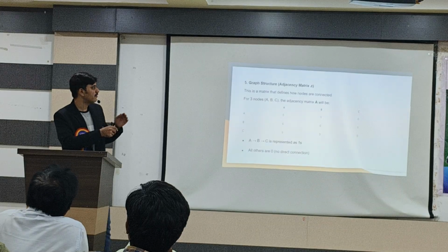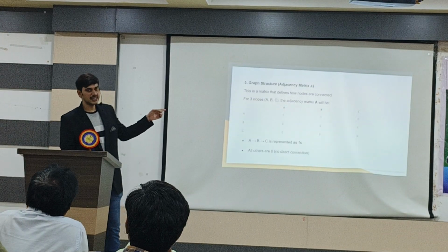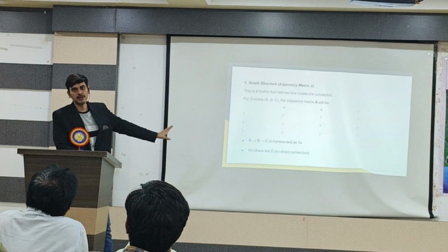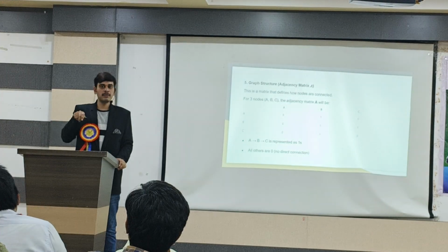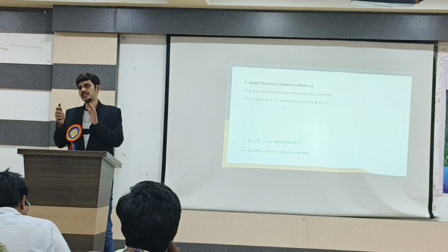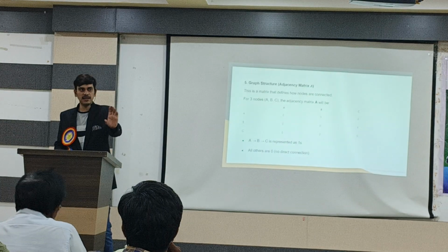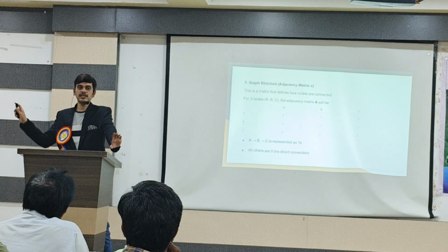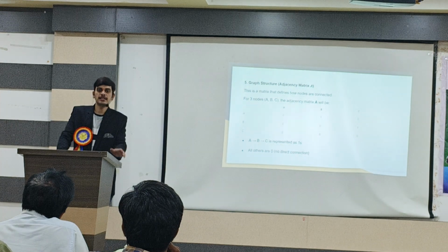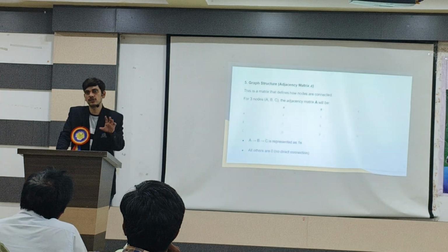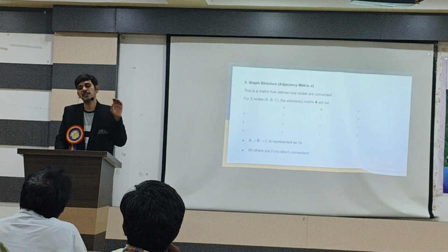So the setup and hold conflict is there. To check the setup and hold conflict, these actions are very important, because in one path it may be setup, and in another path there may be hold as well. So we have margins, like we are setting things right. We check the whole margin, and how much slack is there. And there is a concept of crosstalk also, which we cover at the last.